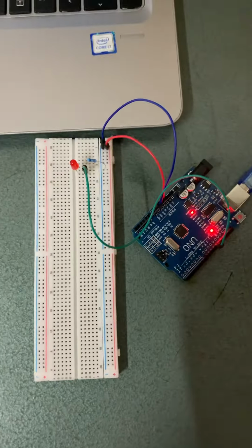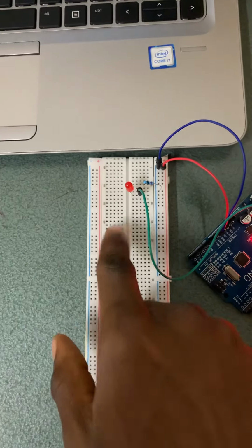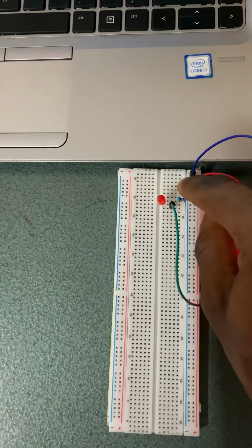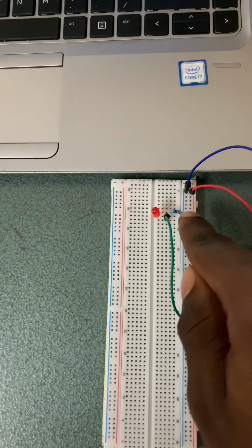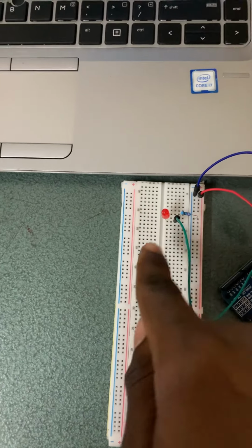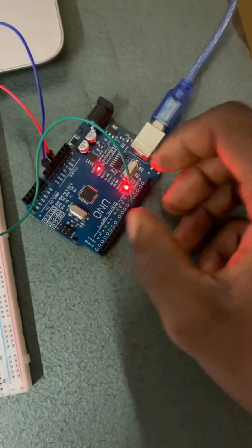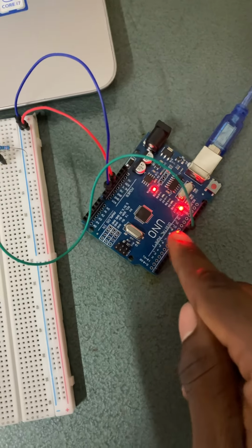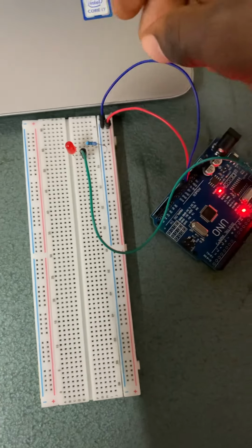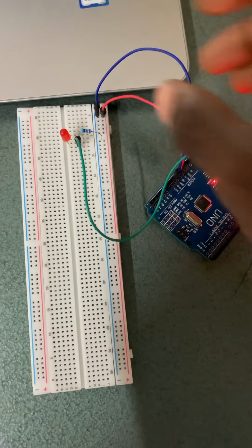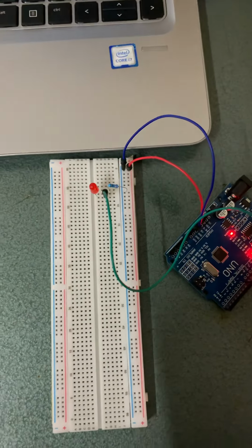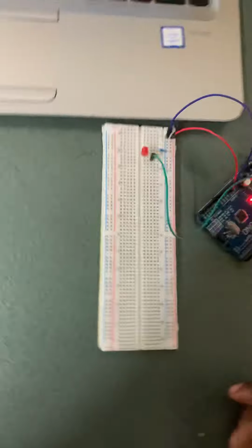Looking at our setup, I placed an LED here and placed a resistor at the negative terminal of the LED and placed it in ground, and I placed the wire at the positive terminal and connected it to, you can see here in my code I made it pin 11, and connected the blue jumper wire to ground and the red jumper wire to the 5 volts. So giving power to our circuit. Now let's go into how it works.